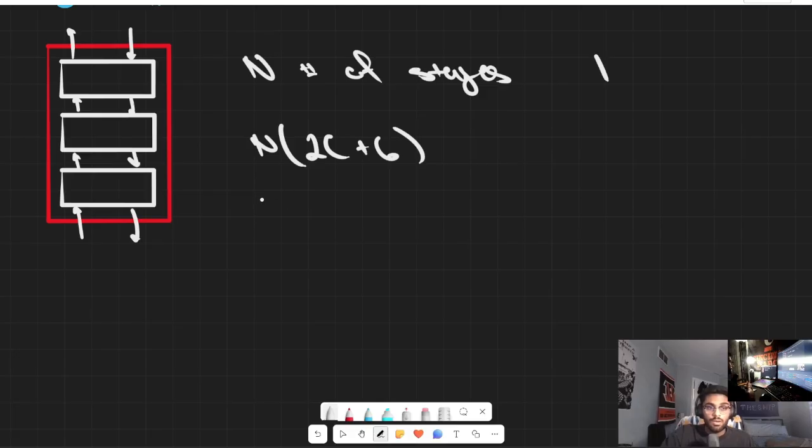Well, I'll write it this way. So 2 times n minus 1, because there are n stages and minus 1 for each of the double counted stages. And each of those stages has a number of c plus 2 stream related attributes.